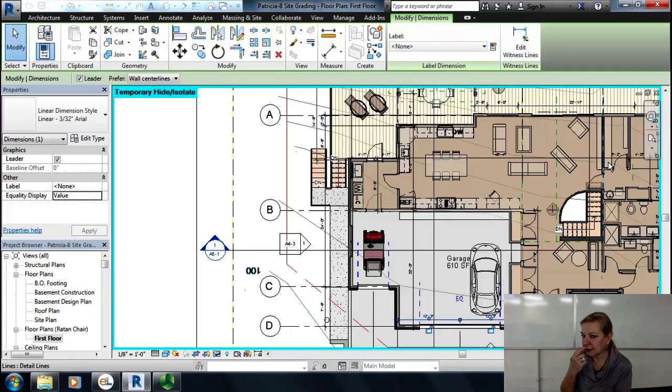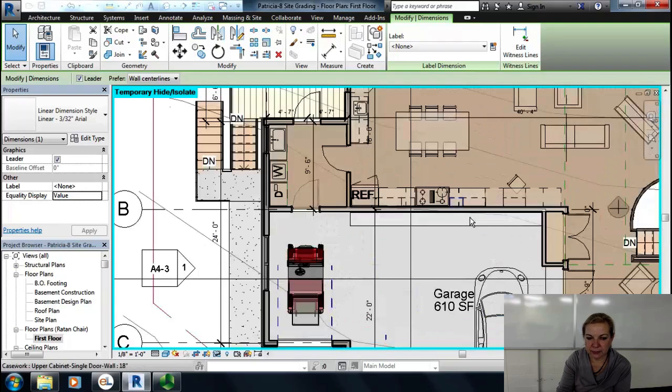So if you had concrete walls, partitions that are fire rated between one room and the other, or townhouse firewalls, or if you want a sound barrier between neighbors, you would specify wall types, and you could show wall types in your legend or note those dimensions. And then if not noted, all standard walls will be 4.5 inches with drywall on both sides.